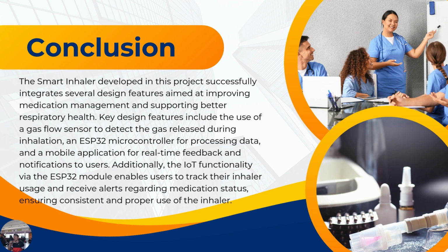We can conclude for our project, the smart inhaler developed in this project successfully integrates several design features aimed at improving medication management and supporting better respiratory health. Key design features include the use of a gas flow sensor to detect the gas release during inhalation, an ESP32 microcontroller for processing data, and the mobile application for real-time feedback and notification to users. Additionally, the IoT functionality via the ESP32 module enables users to track their inhaler usage and receive alerts regarding medication status, ensuring consistent and proper use of the inhaler.